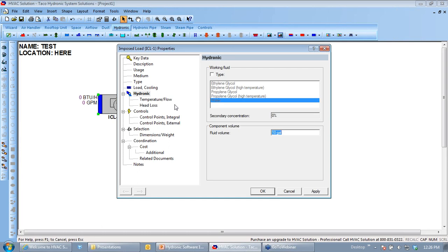The glycol one is an interesting one. Normally, when I draw all the fan coils out, I start with the fan coils on the drawings because that's where I'm going to know the load. I don't know what the load is on the chiller until I've already picked all the loads for my zones. So I normally draw the fan coils first, but I don't typically enter whether I have glycol or not until later on. Later on, I'm going to enter that at the actual chiller, and when I enter the glycol percent at the chiller, it's going to push its way back to all my fan coils automatically, so I only have to do it once. So for right now, I would leave that alone.